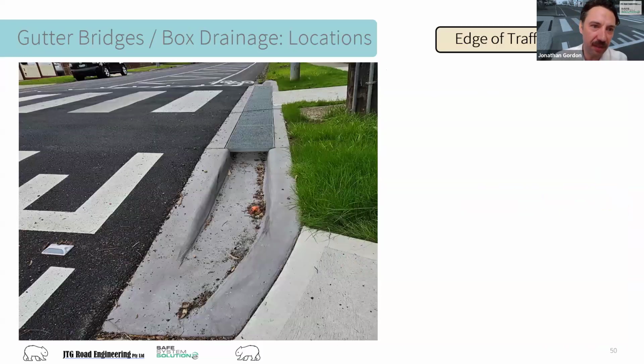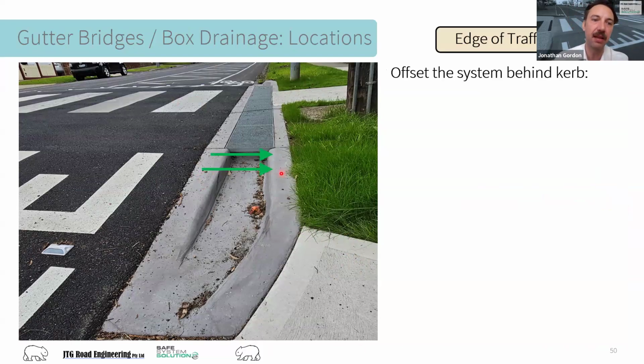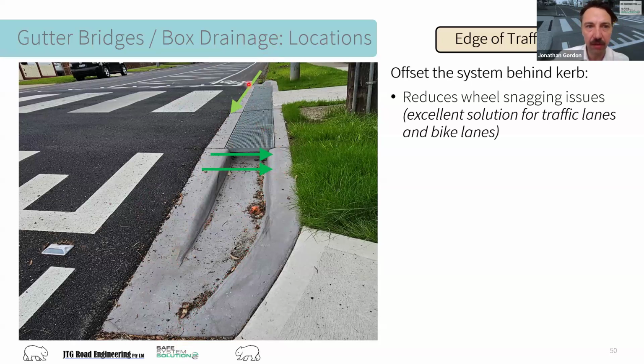Moving on to something that I love to see though, is this arrangement here. Unlike the initial images I was showing where the tire marks were there, and this is sitting in a traffic lane that vehicles have to avoid by just not driving there, this is physically assisting us because it's set back from the line of curb. You can see it's illustrated perfectly by the way that this then returns back towards the curb line. That means our system is pushed away from anyone tracking along the curb line itself, particularly in this example, where you can see some cyclist line marking in the distance up here. That's fantastic for cyclists too, and almost critical for cyclist safety.